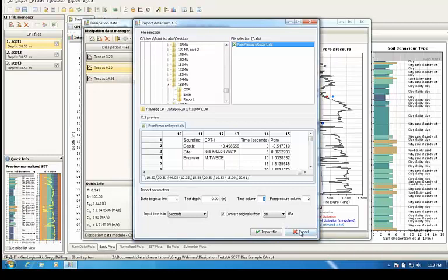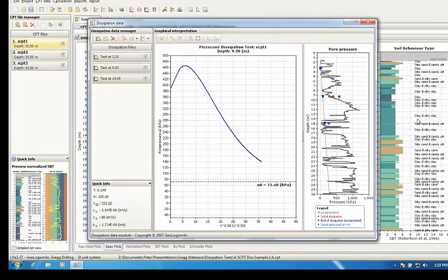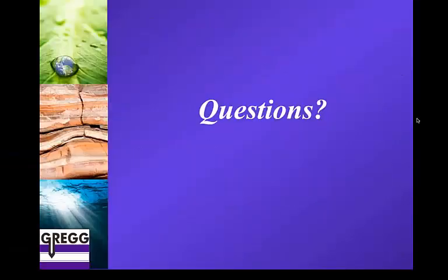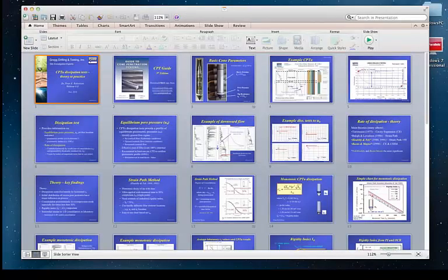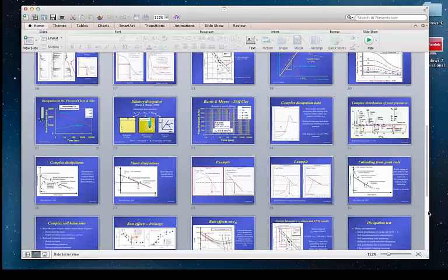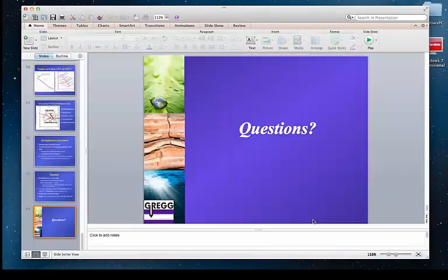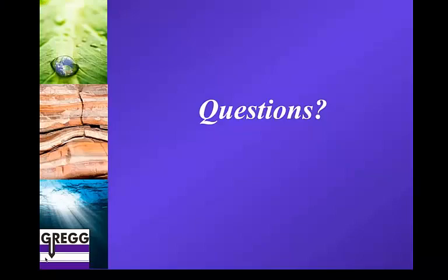I think the guide does have a sentence related to it, where it basically says that the coefficient of consolidation is controlled by the radius squared, and so if the coefficient of consolidation of the soil is unchanged, but just the radius changes, then it's the ratio of those radius squared. It's a fairly well-known observation, but you're right, not often written up.